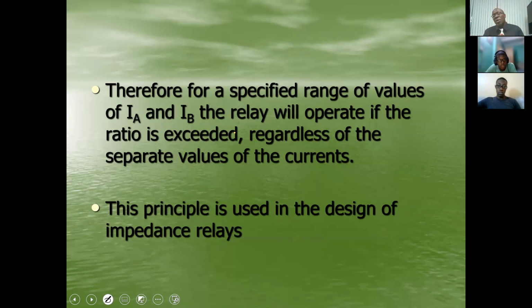For the derived quantities, once we are going to be looking at power or impedance, it means that we are going to be using a VT and a CT. And what we said last week, because of the expense and the size, for your VTs, ideally we use only one VT, so we don't replicate VTs unless, of course, the utility is awash with money and they really want full redundancy. But you hardly ever replicate VTs, and it's not only from a financial standpoint. From a technical standpoint, it's not necessary.